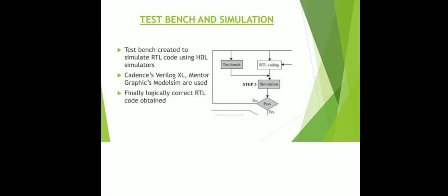Also this can be a process of converting the RTL code into a gate level netlist. It also uses the vendor's cell library of basic gates. So here pre-synthesis can also be done on the IP core blocks. This can be used for RTL behavioral and structural simulation. RTL coding in the behavioral style is used to describe the black box design, where the output of the design is specified for a certain input pattern, and in the case of the structural style, it defines the different components and their interconnects present in the design. So here we can design using some tools or structural patterns.